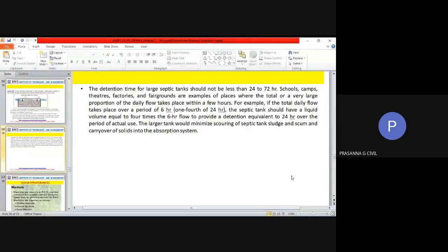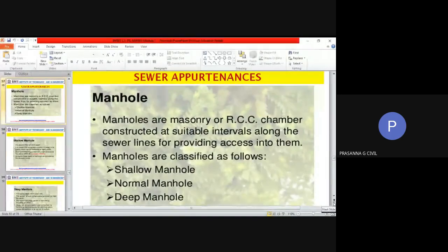So there, if you have the pipe network, here you have the sewerage network, and the appurtenances fitted on the sewerage network go by the term sewer appurtenances, of which the first and most important one is a manhole. So why the term manhole? So if you go to a main sewer, we talked about trunk sewer or main sewer, branch sewer, laterals, etc. Laterals are very small pipes, so the size of your manhole also will be very small.